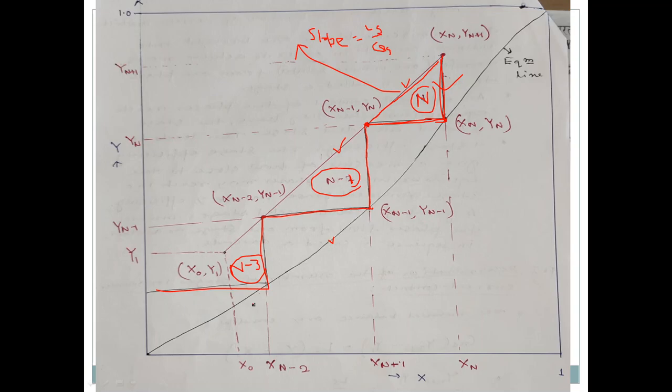And for a particular case, if the tray spacing is 1 meter, and there are 30 plates from the equilibrium, the height of the column will be 30 meter. And in some cases, if the number of stages is 100, then it will be 100 meter. Because I want to construct this equipment, mass transfer equipment, I know this is circular. Now what other things do I need to do? I have to know what the diameter will be and what the height will be.